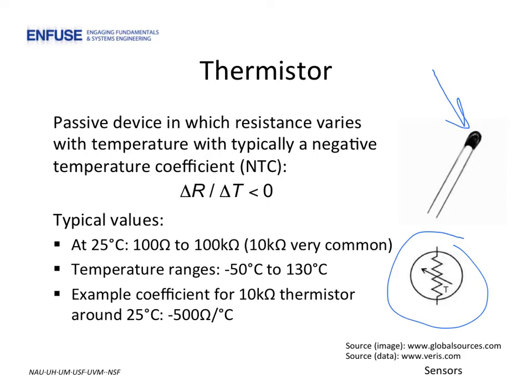Most low-cost thermistors have resistance that is inversely proportional to the temperature. These are referred to as NTC, or negative thermal coefficient devices, in which the change in resistance over the change in temperature is a negative value.